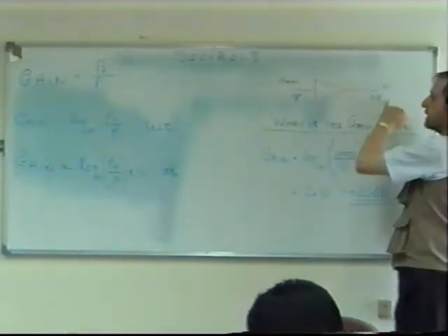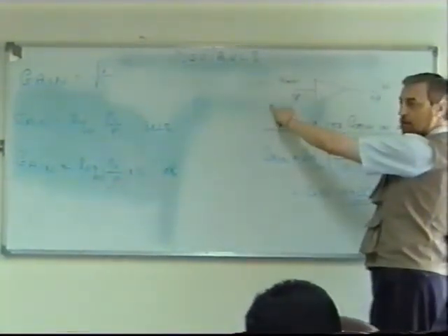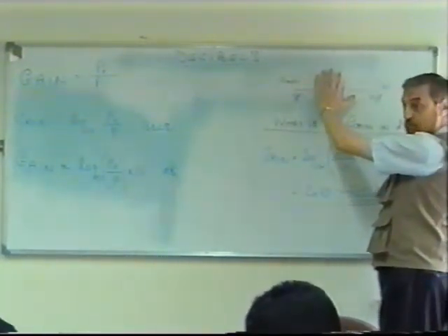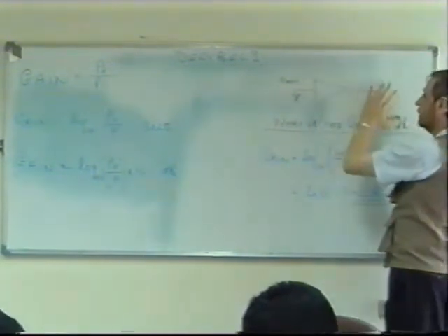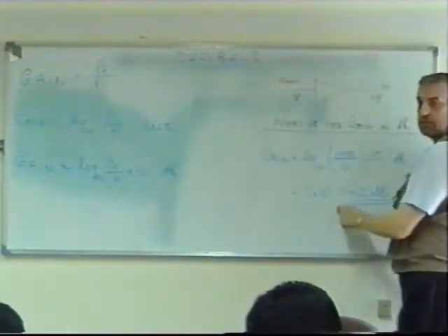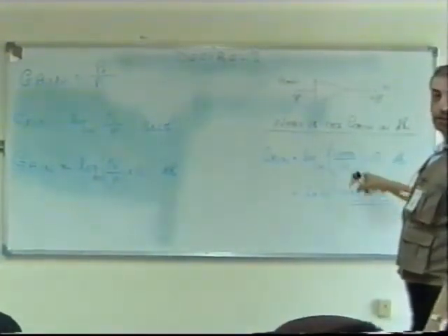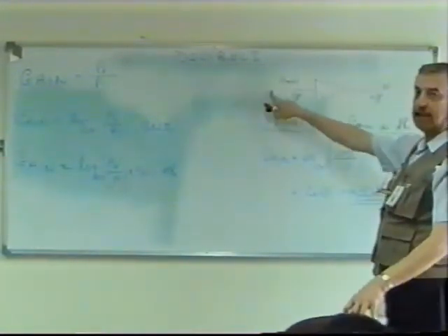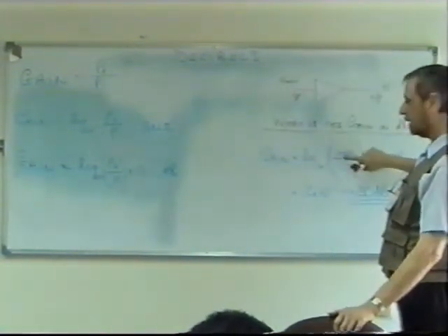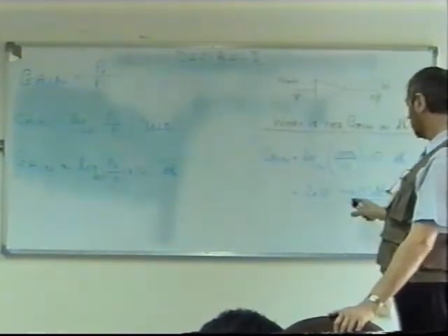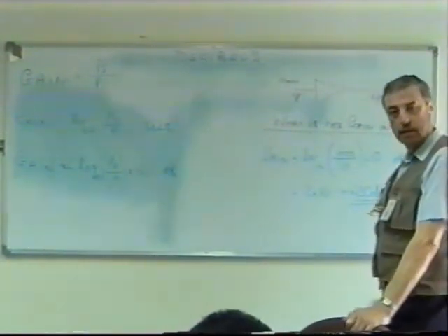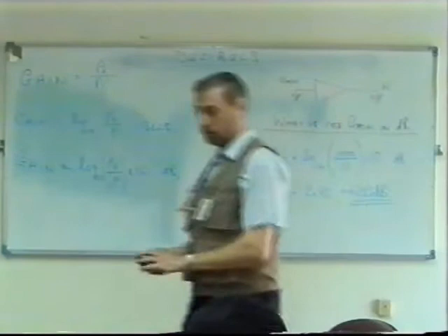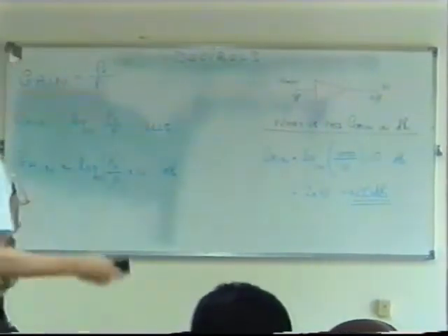Now, if this power was less than the input power, this could be, for example, an attenuator to reduce the level of the signal. Then, of course, we would end up with a negative number here because the ratio here would be less than 1, wouldn't it? For instance, if I put 1 watt in here and 10 milliwatts out, it would be negative. Yeah, all we do is reverse this, and we end up with minus 20 dB as a gain. So, that tells us something for a start.